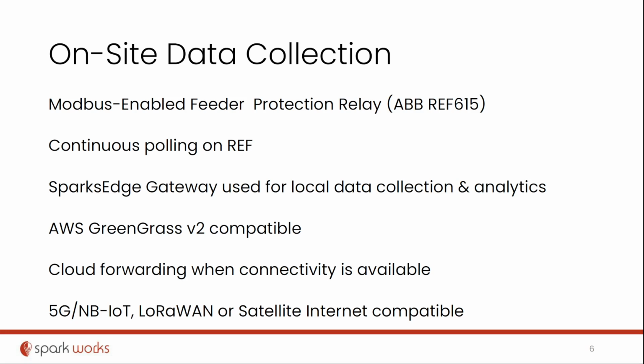Data are kept locally, and then they are forwarded to the cloud using any kind of network that could be available in the site, either a data connection, 4 or 5G or NB-IoT connection, a LoRaWAN, or a satellite internet if it is available.